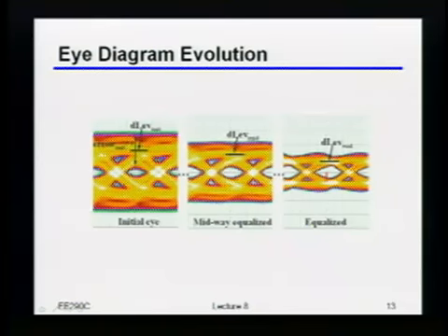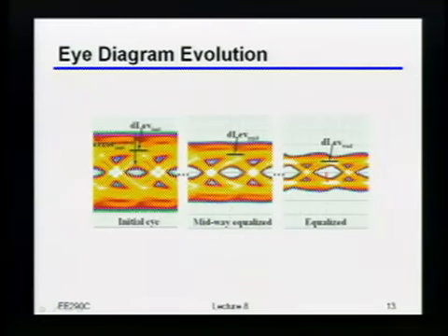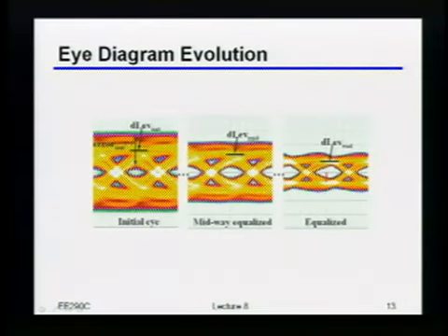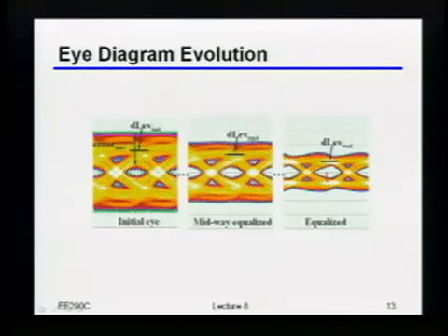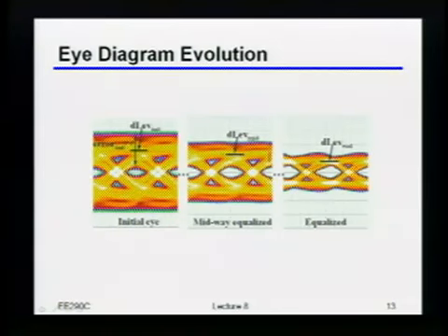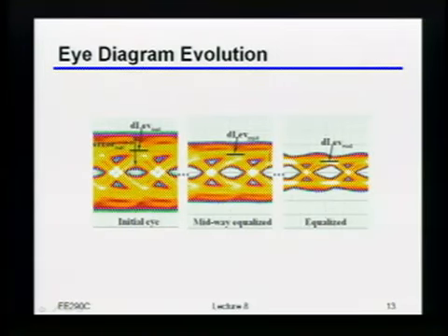So basically you said this is a zero forcing equalizer. Actually, even if it was MMSE, the trick is that because I have a fixed peak swing at the transmitter, when I start putting stuff into the equalization coefficients, by definition I'm attenuating the DC. So that means the data level is going to be coming down as I run that equalization. That's exactly why there are a lot of movies where you see this eye breathing in some sense. Initially, you don't really know what the data level is, and so things move around a bit. And then once you lock, it all smushes in.